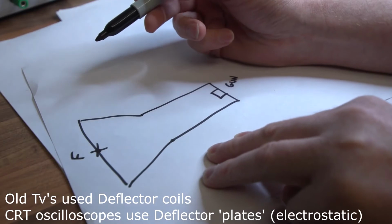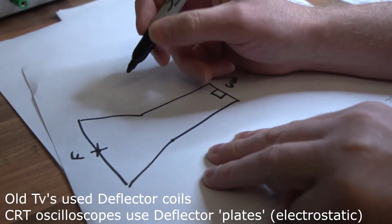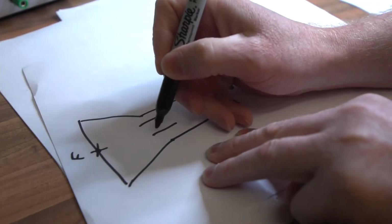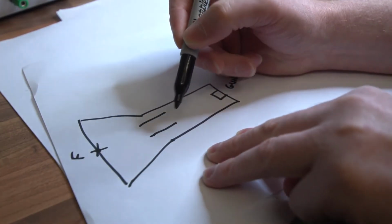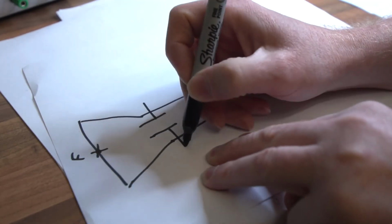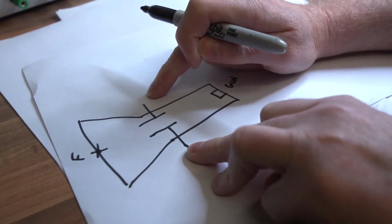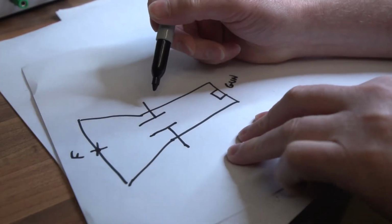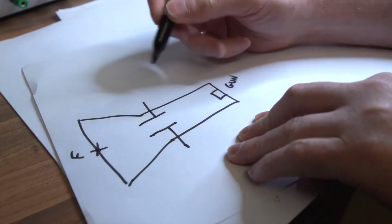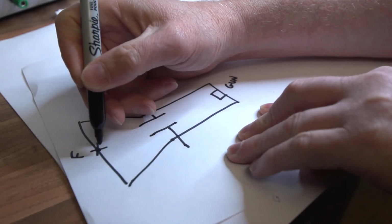But in an oscilloscope they do it the other way, which is using electrostatic deflection. And electrostatic deflection just uses plates. So inside you actually have 4 plates, but I'll only draw 2 right now for the purposes of the diagram. And on those 2 plates, you can apply voltages, positive or negative. Like I said, if you didn't have any difference in the voltage across the deflector plates, the beam would just go straight through and hit the front in a dead straight line.